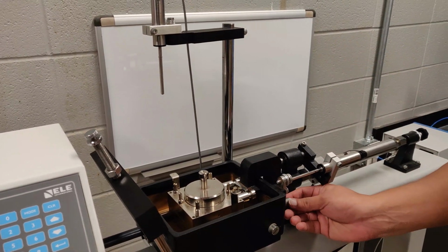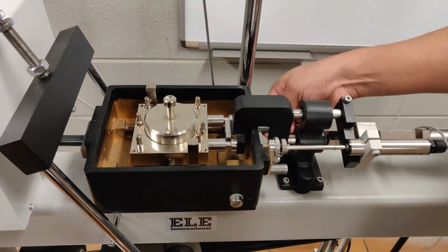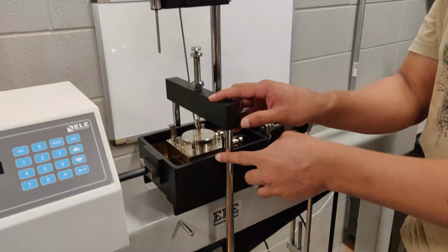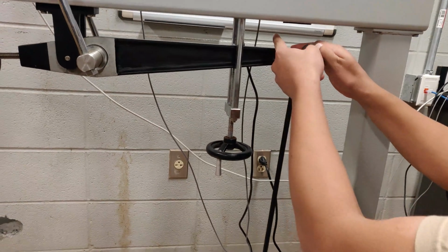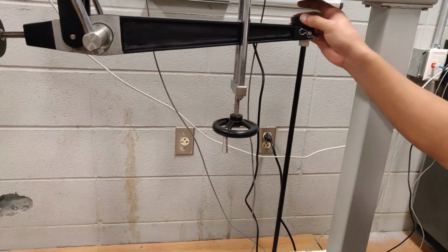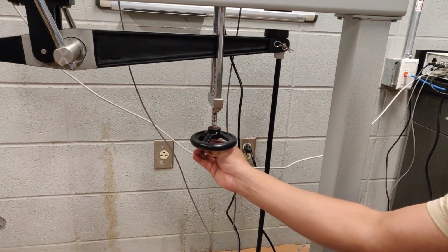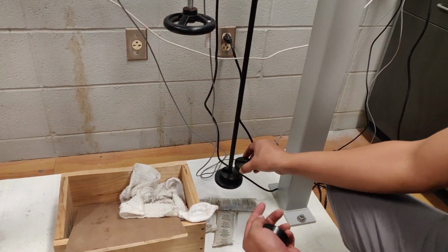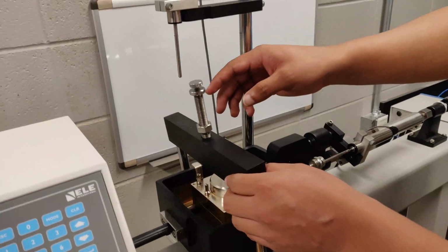Now we have to tighten the screw at the bottom on both sides. Before you tighten the screw, you need to first make sure the load hanger is nearly horizontal. You can put some residual load in order to make it horizontal. Adjust the screw to make it horizontal, and after that you can place your load in the load arms, and after you put the load, now you can tighten the screw.